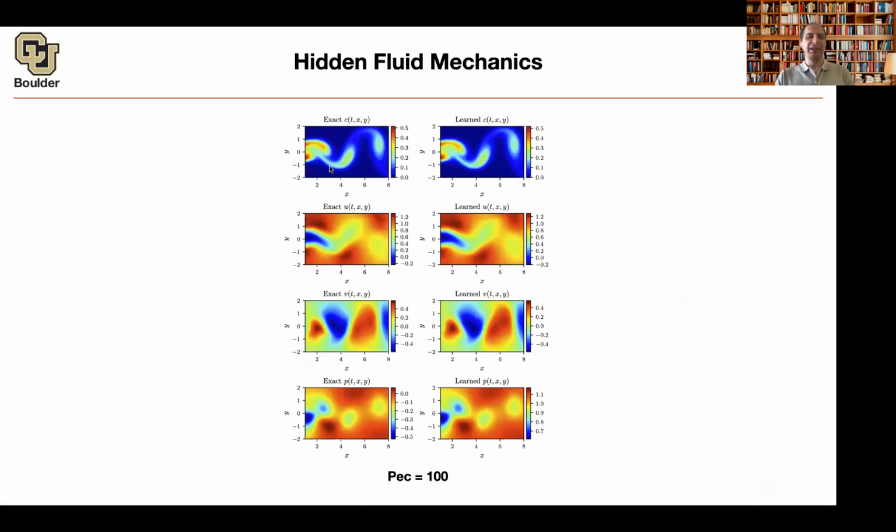That data is like the concentration of a passive scalar, basically your dye. It's passive because it's not going to interfere with the dynamics of the fluid. It's getting advected by the fluid, and it's diffusing because you have some diffusion constant for the dye. And that diffusion constant, if you non-dimensionalize your equation, is going to give you your Peclet number.